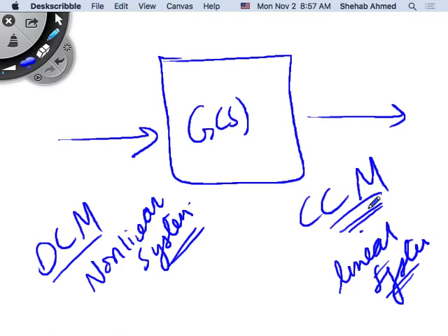Also, what happens is the transfer function changes, meaning the gains, also the output changes. So maybe in a linear system, you press your foot on the pedal, push it 1 centimeter, you increase the acceleration by 20 kilometers per hour. Another 10 centimeters, another 20 kilometers per hour, and so on and so forth. In a nonlinear system, maybe at the beginning every centimeter is 10 kilometers per hour, and then every 10 centimeters becomes 20 kilometers per hour, and then every 10 centimeters becomes 30 kilometers per hour, right? So you will have to control it differently.